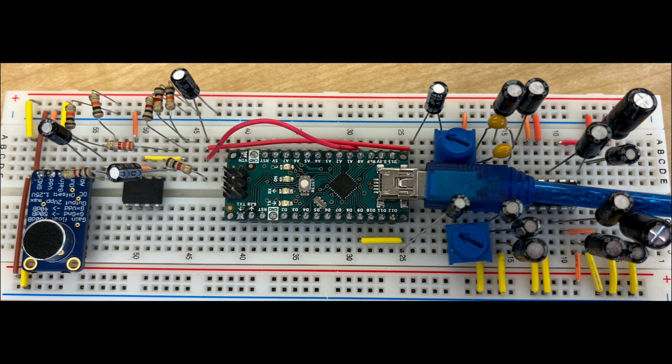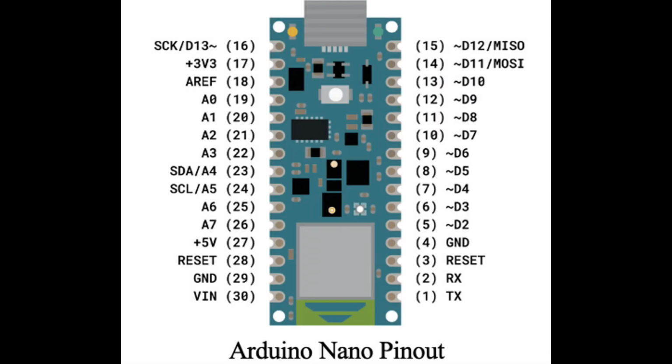Then the filtered signal is sent to the Arduino, which produces the reverb effect, and then to the TA2025B amplifier, where it gets further amplified before being outputted to the speakers. One of the key features of this project is the real-time digital reverb effect, achieved through custom code written for the Arduino Nano. The program continuously reads the audio signal input from one of the coupling capacitors after the bandpass filter and processes it with a delay to simulate the reverberation effect.